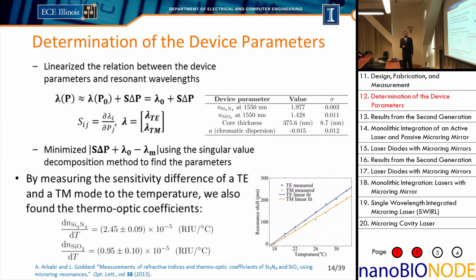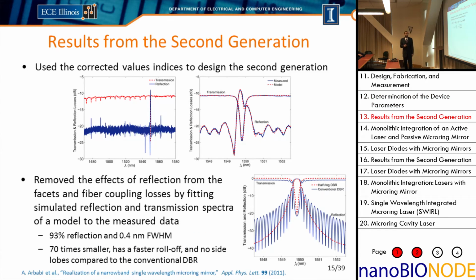All these other resonances all agree with, if I give you those 4 quantities, like the resonance location of one of the resonances for TE plus the free spectral range for TE, the resonance wavelength for TM plus the free spectral range for TM, those 4 parameters pretty much determine these entire spectra. So the rank of our measured, or of our singular matrix S, is only 4. So we're able to achieve very accurate results for our model parameters for 4 parameters.